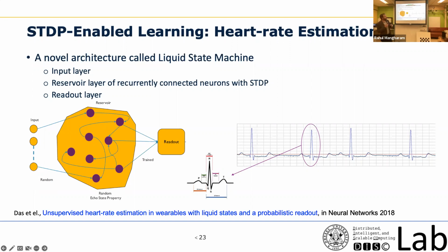Very importantly, what we had to try to do is understand the QRS complex. Now, you might say QRS complex is a very known case study, right? With the Pan-Tompkins algorithm, you can very easily detect it. However, there are a lot of problematic scenarios. For example, one of the use cases that we have dealt with is people with COPD. Their heart rate QRS complex looks extremely different from a normal QRS complex.